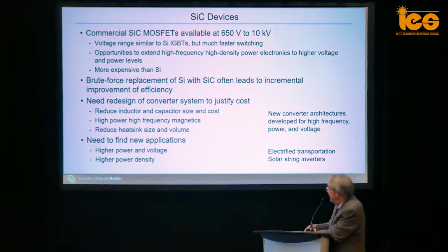Silicon carbide devices are very interesting to me right now because they represent a pushing forward of the limits of power electronics applications to much higher voltages, much higher currents, while moving to higher power density. These devices are replacing silicon IGBTs, but they have much faster switching, so we can run them at hundreds of kilohertz instead of 10 kilohertz. And we can extend high-frequency power electronics to much higher voltage and power levels. But they're more expensive than silicon.